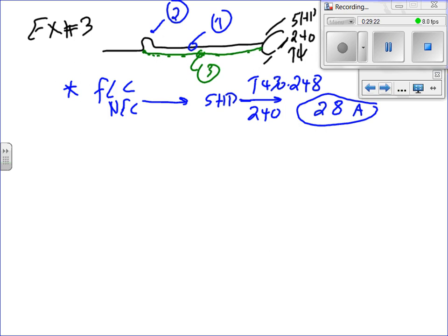Okay, now we start our business. Now we start number 1. The first thing is to find the full load current from the NEC. That's step 1. You can't do anything without it. Okay, now I need to find the branch circuit conductors. Fancy name, huh? Branch circuit conductors.